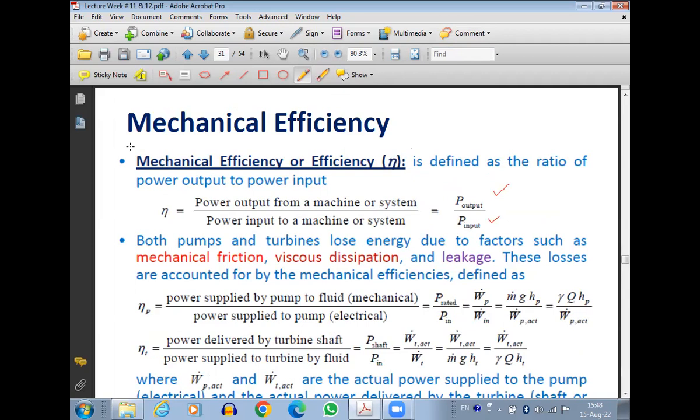There is a mechanical efficiency and an electrical efficiency of that generator also. The other thing is the fluid power. So the fluid is moving, so it has power. When we talk about efficiency, it's always power output by power input, but it depends which one is the fluid power and which one is the mechanical power. This is the thing that needs to be understood.